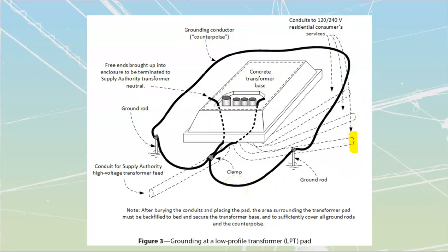What we do when we place this is all going to be bedded on gravel. So you're going to dig a hole, you're going to have gravel placed around it for drainage. Then you're going to get this transformer base itself that is going to be craned in. You don't mold this thing, this is going to be pre-made. Almost everyone in the province, at least out here on the coast, comes from Langley Concrete Products. They've got a big yard out there and they're an approved supplier. They mold those things and deliver them. So we get one of those that's going to be craned on there.